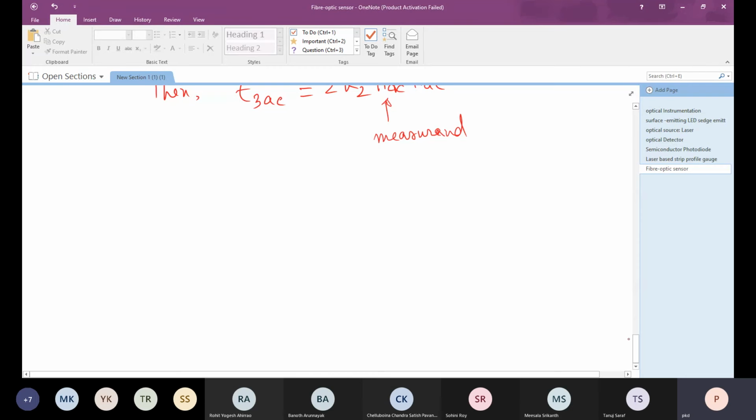Now the Mach-Zehnder interferometer is simple to construct, and because of the closed loop configuration it is also to some extent robust, but as I said it is dependent on vibration and also on temperature. So usually the temperature of that interferometer is monitored.